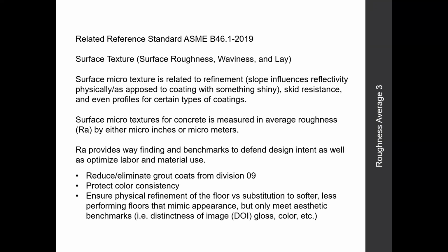And one of the great things about doing that is if your constructor takes measurements, just like you would with sandpaper, and kind of measures what the starting canvas is at, they don't accidentally go into too abrasive of an initial procedure. Literally go back, and let's say the concrete was a certain level of smoothness, and so they could start and have reduced labor going forward. If they make it rougher by not measuring, then we found at this particular training that the contractor had added not one but two additional passes with diamond tooling for aggregate exposure and initial polishing of the grind, as well as two passes on the final refinement.